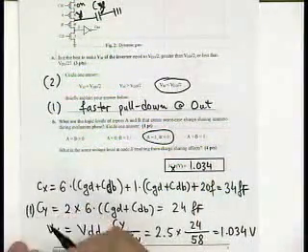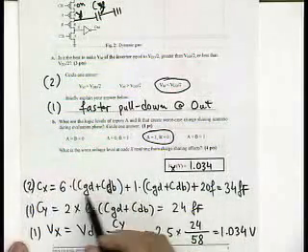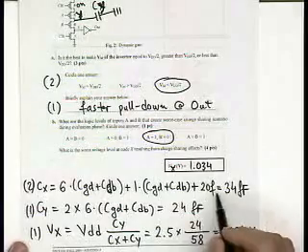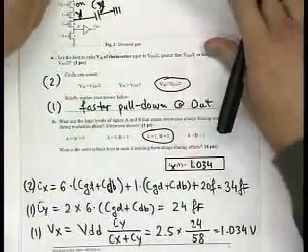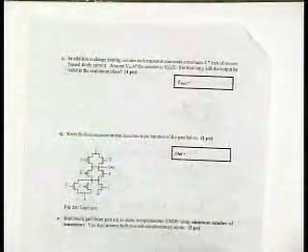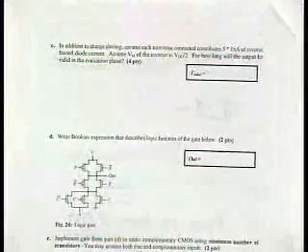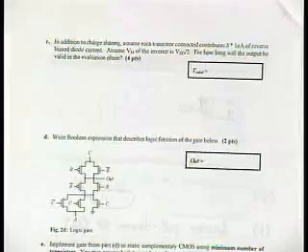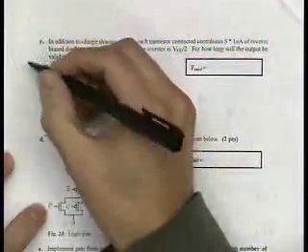This was 1 point, this was another point, and this was 2 points. Basically 1 point for transistor capacitances and another point for this input capacitance. So now the next question is, in addition to your charge sharing, what happens if each transistor further contributes some reverse biased diode current? So what we have in this case is the following equivalent model.